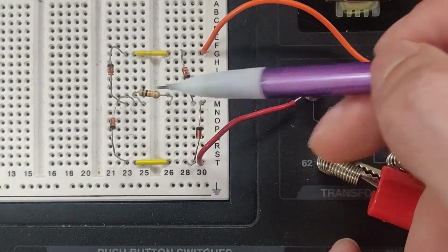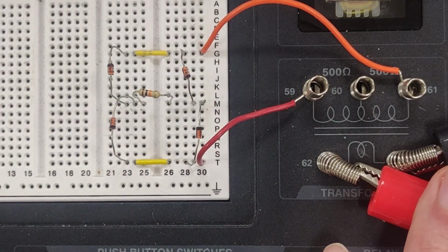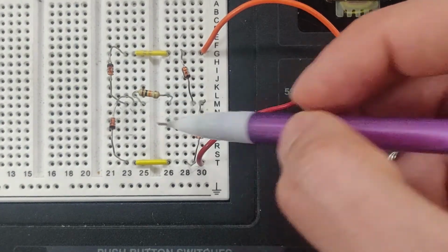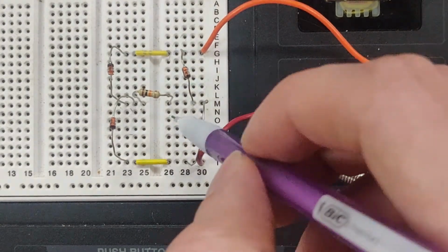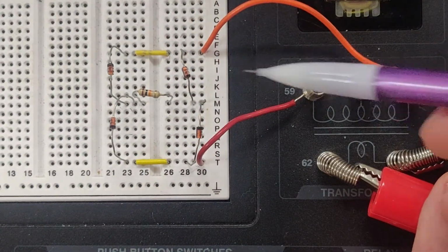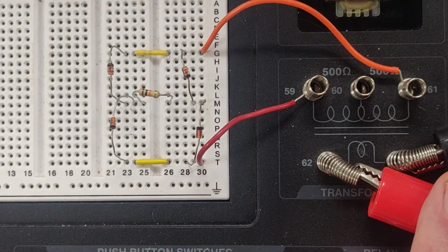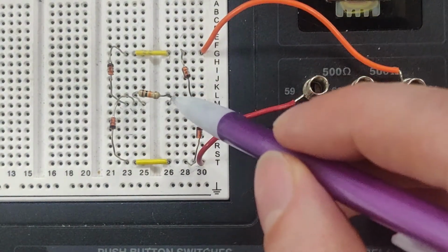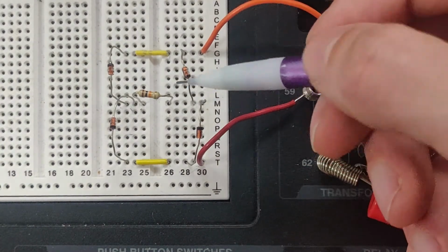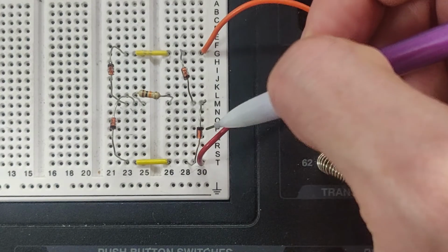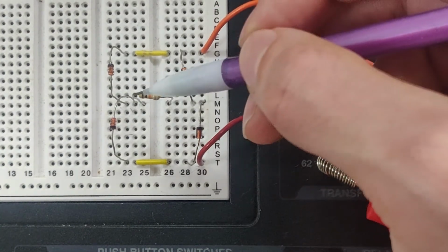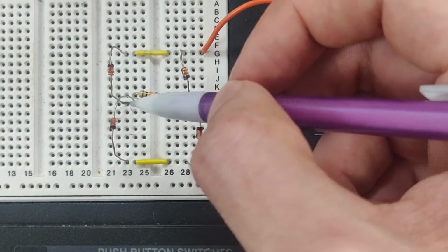Now it can either go through this diode or jump to this resistor. If you look at figure 8, you can see that this R1 resistor is a 10K ohm resistor. It looks like it's going around the circuit, but having it in between the two columns of diodes is essentially the same orientation. If you look side by side at the lab manual and the circuit right here, you should see that having the resistor in between the diodes is the same as how it's drawn in the circuit diagram. But anyways, current comes down here, going through this diode, and now this diode is in reverse bias orientation relative to the flow of current. So it's going to pass through this resistor, and then it reaches this junction.